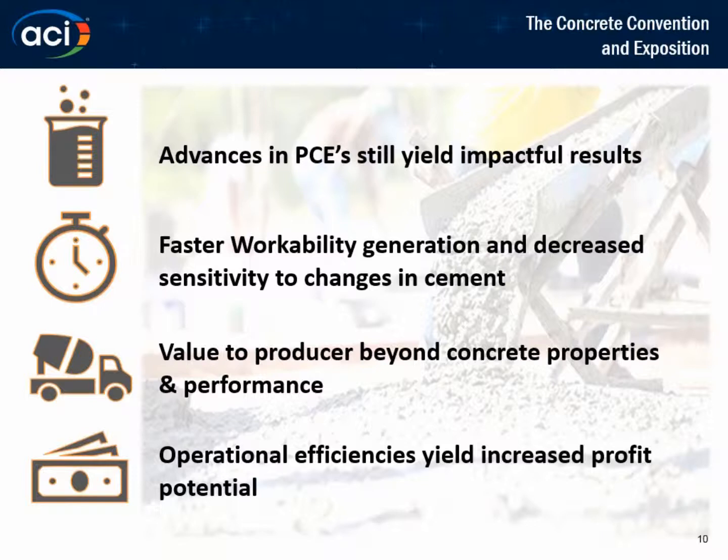Other questions? Right here. In the experiments that you have conducted with different sulfate sources, different sulfate, no. So when you say different sulfate sources, what are you? Different types of gypsum, plaster, so the sulfate available in the cement. Yeah, so no, our sulfate analysis was done based on whatever cement we chose. We did an internal quick pore solution test to quantify the sulfate that's there, and we just went with that to determine where we stand in terms of the sulfates, but no alternate types of sulfate.